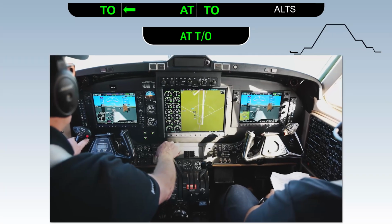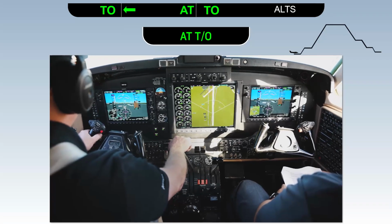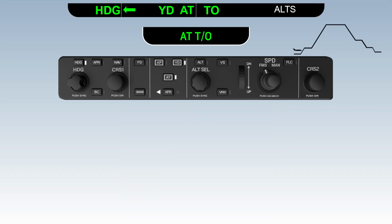When AT takeoff becomes active, the pilot should follow the throttles with their hand in case there's a need to abort the takeoff. During the initial climb, the yaw damper can be engaged. Above 400 feet AGL, the pilot can select the desired lateral and vertical modes and engage the autopilot. For the lateral mode, we'll select heading and follow the flight director to 050. For vertical guidance, we'll select FLC to perform a constant airspeed climb.